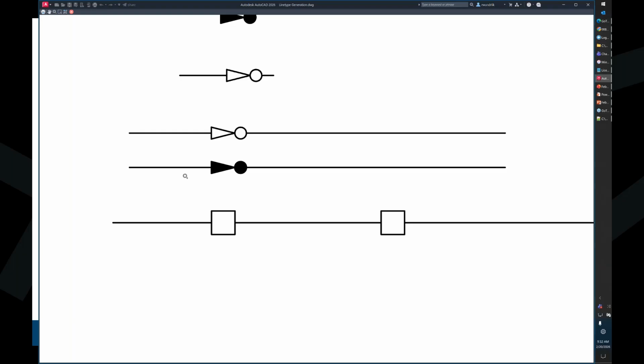You cannot use solids. Shapes can only be generated from lines, arcs, and circle segments. You can use a polyline, just understand that sometimes the behavior isn't great with polylines, so I always recommend lines, circles, arcs. That's it. Can't use solid. So this is as close as you can get to a solid fill.